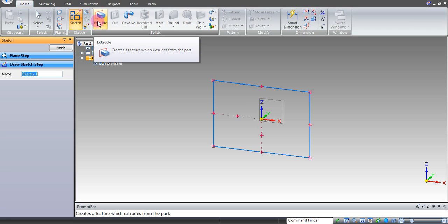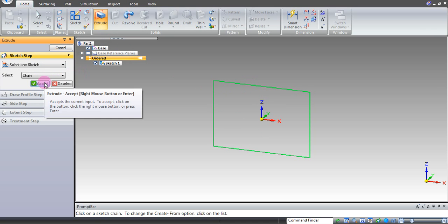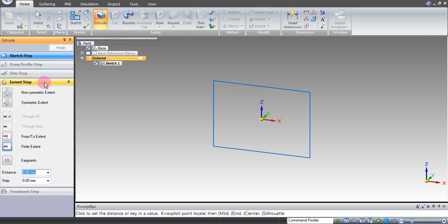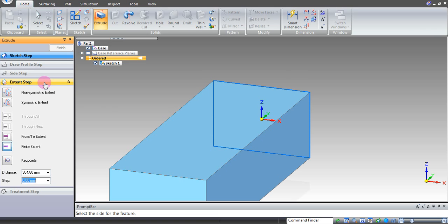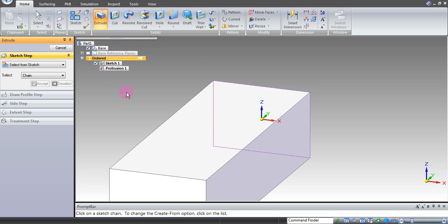There are different ways to create 3D models. You can extrude a sketch, which is basically saying, I want to take this sketch and I want to raise it up maybe a foot, and it'll create a foot long solid model of your 2D sketch. You can also make cuts in your sketch, make holes, round edges, or revolve a figure around a central axis.